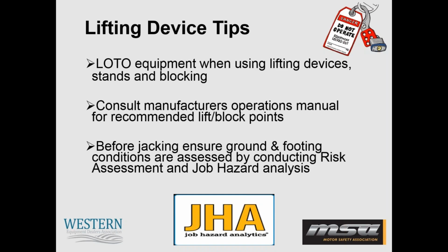So the manual is a great resource, or you can always contact the supplier and they can give you that information as well. But again, before you get under there and start jacking up your equipment, you want to take a look at your conditions and the surroundings and the task you're doing, and conduct a risk assessment and job hazard